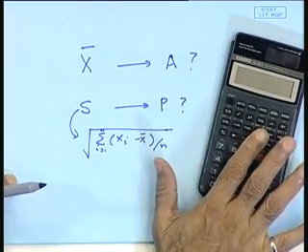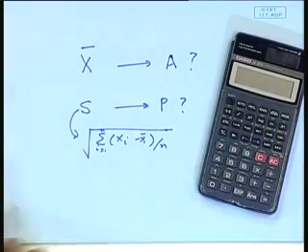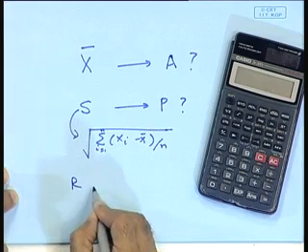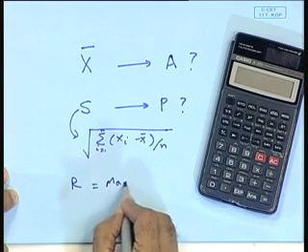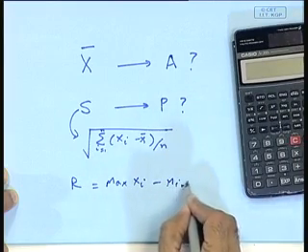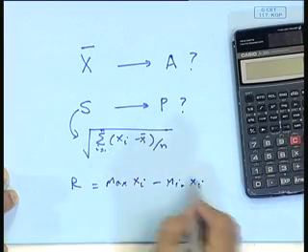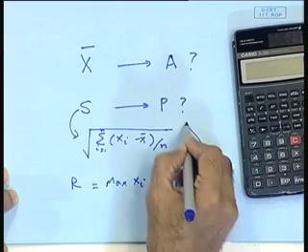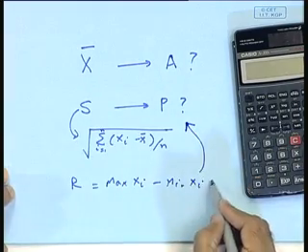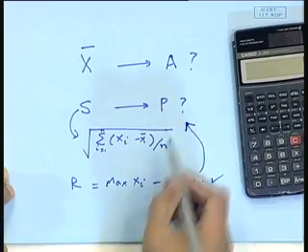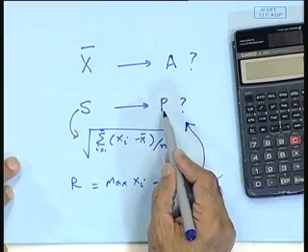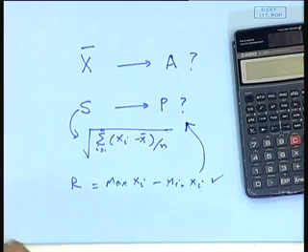So what have we done? We've said we will probably use the calculator to find my X bar quantity only. But in place of S, we use range. And range is just max xi minus min xi. And this will do the same job. It will also let you control precision just as S does. This will do the job just as good. So in fact, I can control accuracy using X bar chart. I can monitor precision by looking at the R chart.